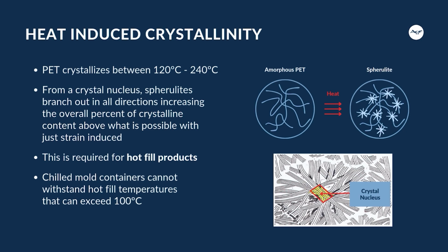It's undesirable to have that type of crystalline structure in a preform or in the container. You can actually take a water or CSD bottle, and if you're operating at too high a preform temperature, it'll become hazy. And that haze is a result of growing thermally induced crystalline structure throughout the container. And that's telling you you're way too hot.